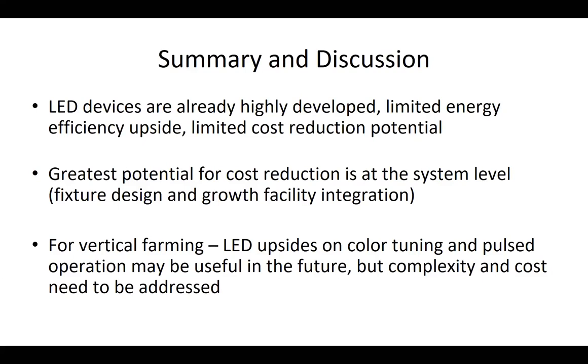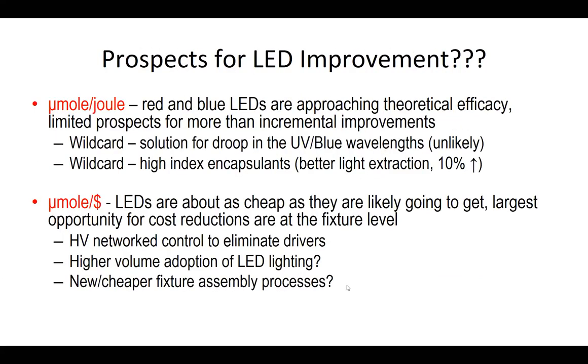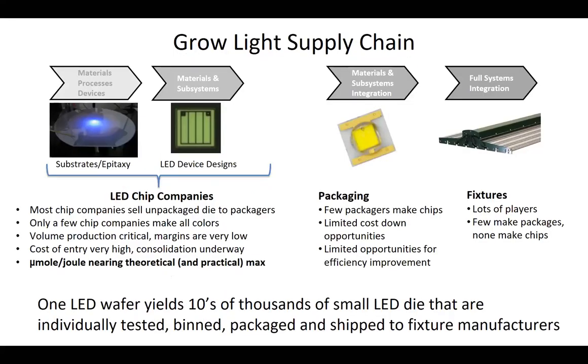Tough question. It really depends upon how the LED fixtures are made. So the LED chip itself is remarkably reliable. And I'm going to go back to an earlier slide where I talk about the supply chain over here. And generally as a user, it's the mean time before failure of the fixture that you're really worried about. Now, you can get a failure of the LED chip, you can get a failure of the LED package, and you can get a failure of the driver electronics going into the fixture.